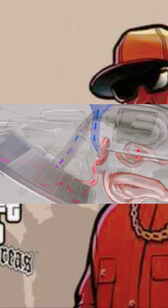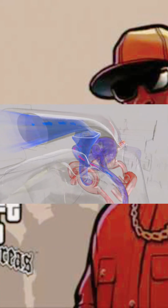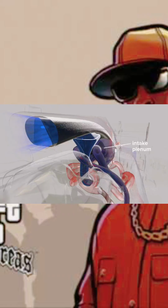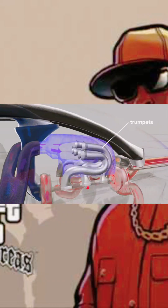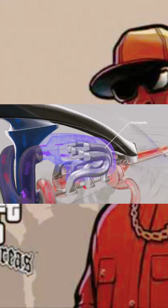The now cooled air passes through the special split ducting that feeds separate intake plenums. These are chambers designed to keep air pressure balanced between cylinders. Intake trumpets extend into the plenums for specially tuned air delivery to each cylinder.